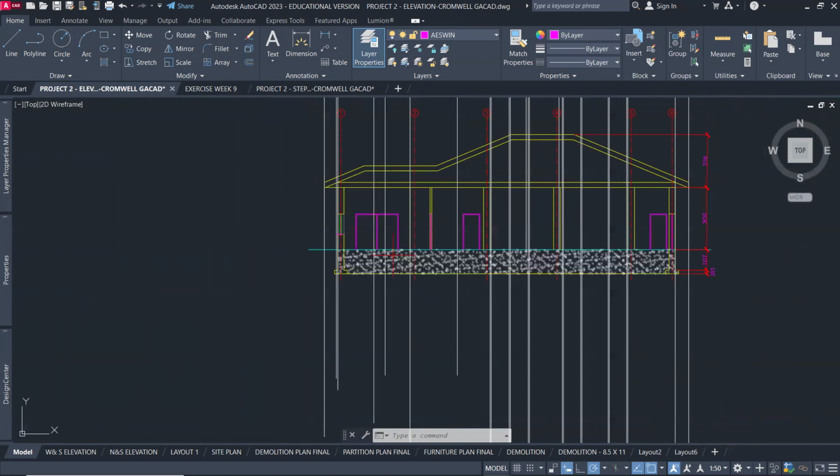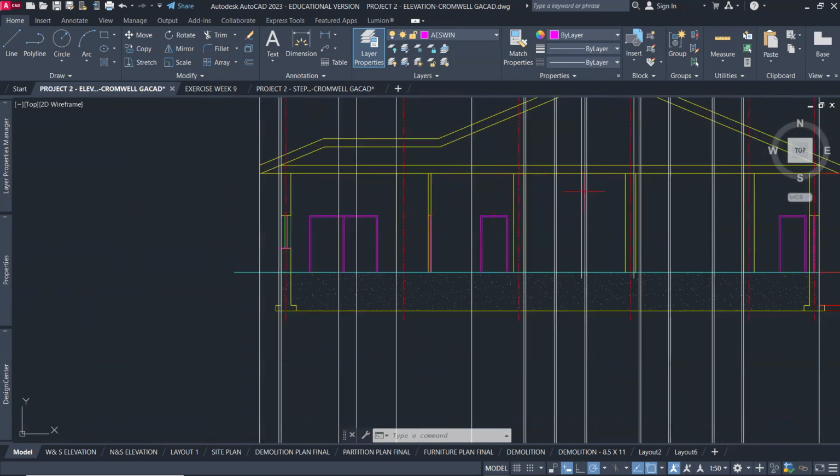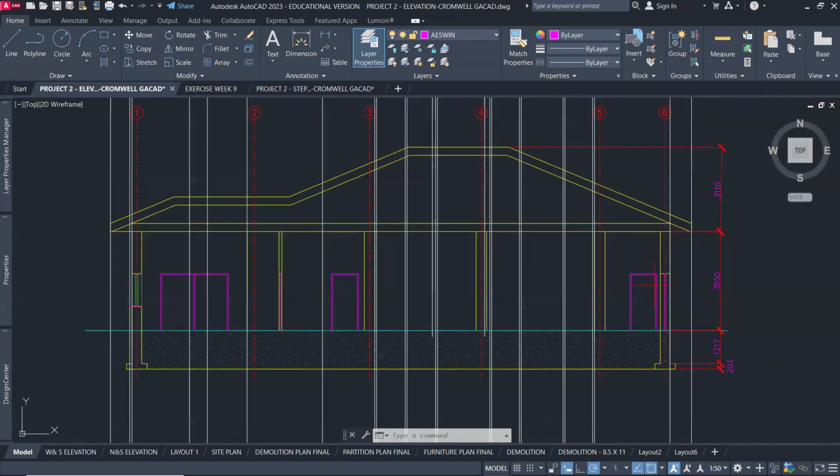And then the rest, again, you do projection. You draw the walls, and you draw the doors, and then you draw the roof. Now here, we're just doing the outline of the roof, and then you can say C, truss, or roof detail. So you don't have to show the detailed drawing of the roof because we're printing this at scale 1 to 100. It's a small scale. The general profile of the section of the building is enough.